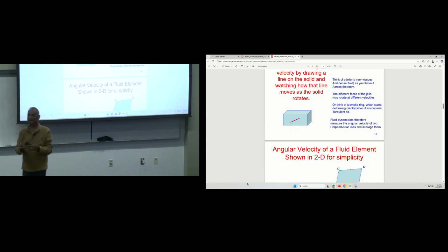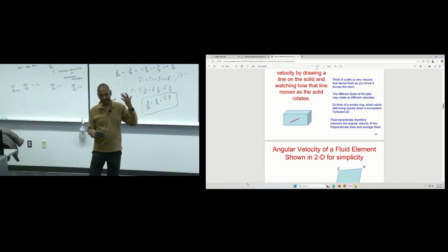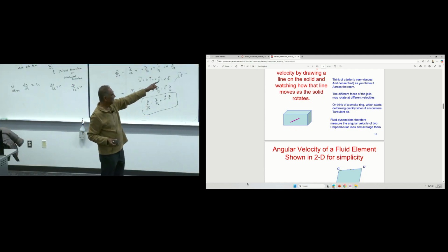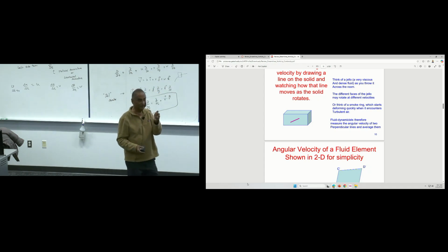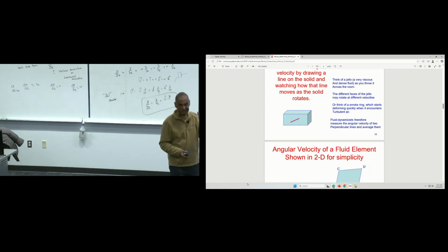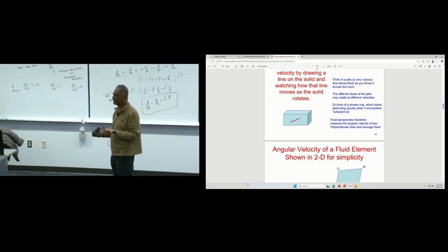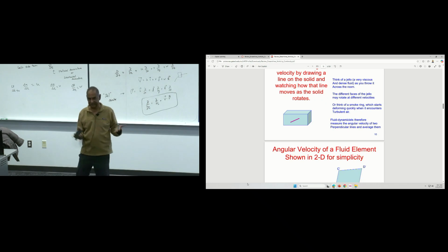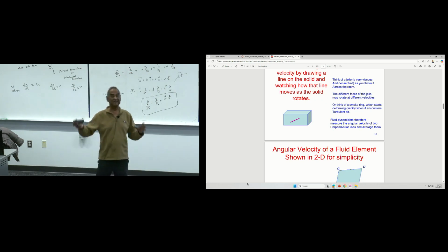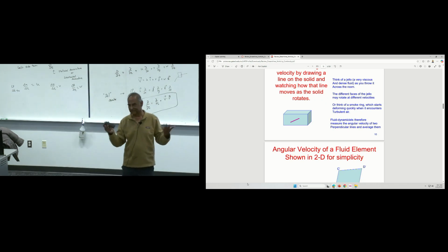As you know, we have an indoor flying lab. We have helicopters flying around all the time. They put reflective stripes on the helicopters. Then they make the room dark. They use a strobe light and take a picture of it. So the rate at which these strobe stripes are turning gives you an indication of the angular velocity. So you could see how quickly I can rotate this vehicle, how much thrust it takes, and all kinds of good stuff they could do with that.